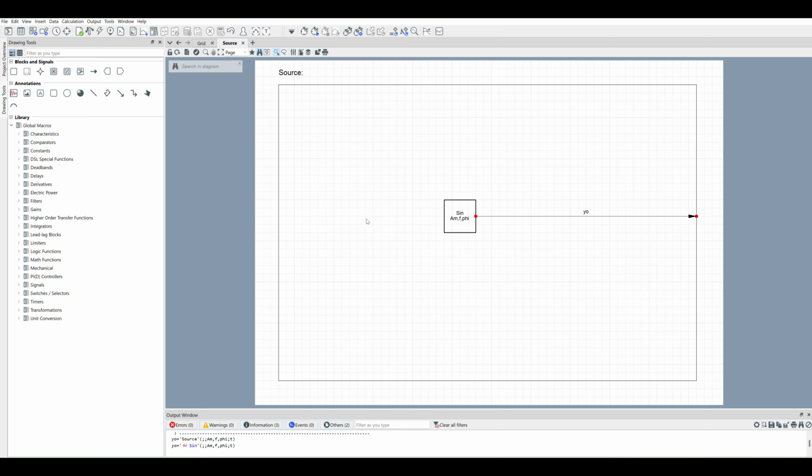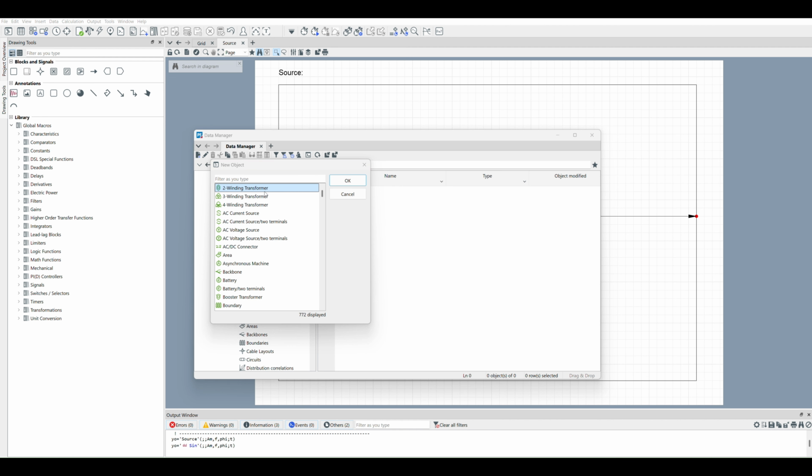It's something like the composite model, the composite frame that we had, but here now we should make a common model in the PowerFactory. For doing that, you should click on Data Manager, then go to the Your Grid and click New, and then you will have this window. So here you need this DSL model. Just click OK, and you will add it to your grid.